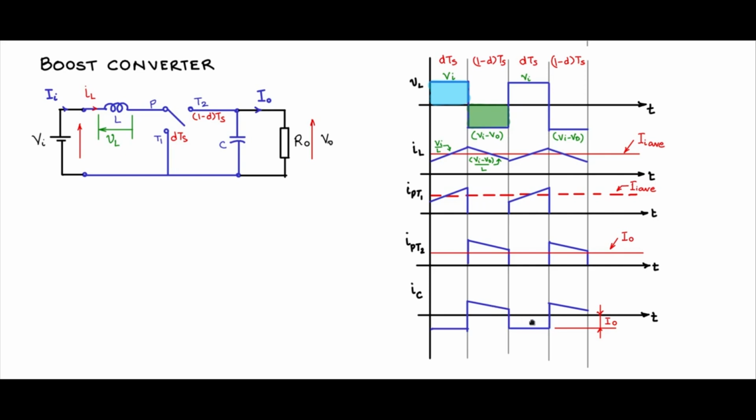Now the area under this IC curve will be the charge Q. So in every cycle, this amount of area will be delta Q. Like in the buck converter case, we will try to find what is delta Q. And delta Q we know from physics is C into delta V. So what is delta Q? It is the area covered under the IC envelope.